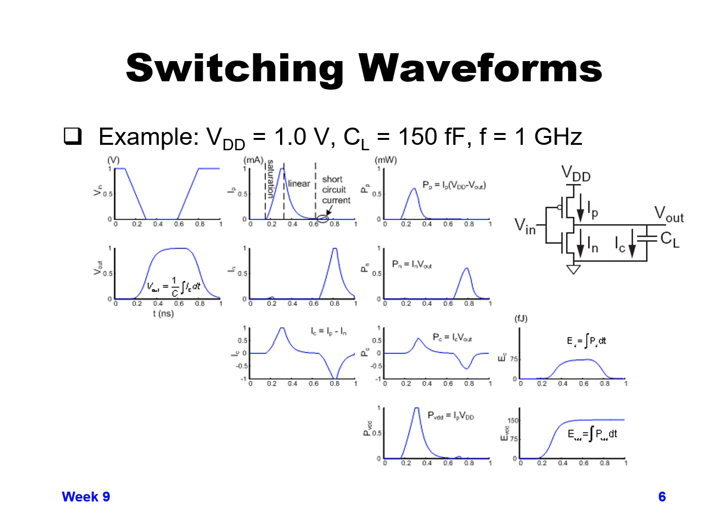The second column from the left shows the current going through the PMOS device on top. The second from the top is the current going through the NMOS device, and the third one is the current going through the capacitor. Let's start with the current going through the PMOS device. As the input is switching from high to low, the PMOS starts turning on as the voltage across it from VDD to VN, the VGS across your PMOS, starts increasing.